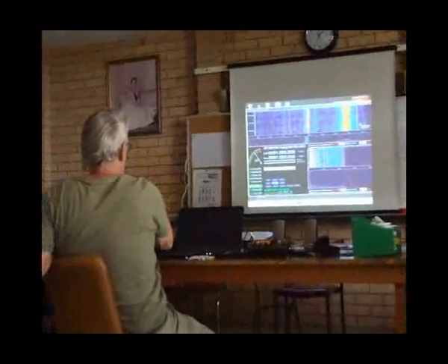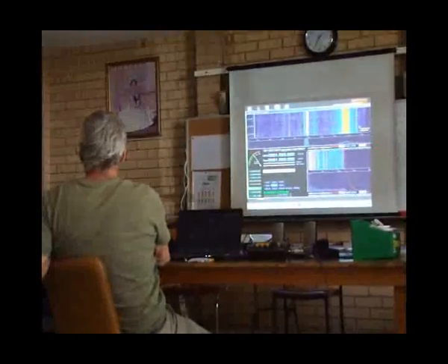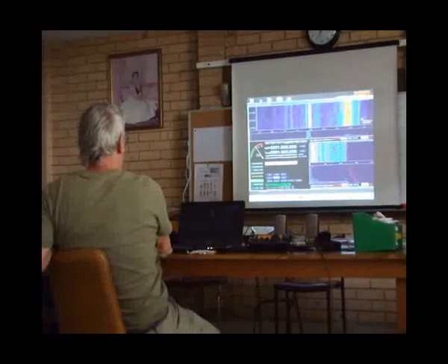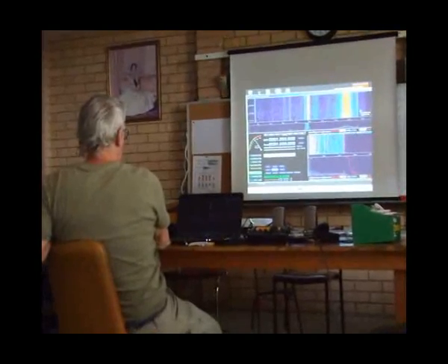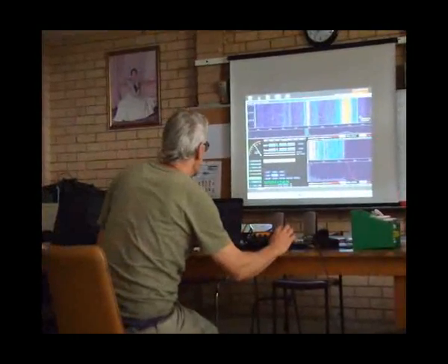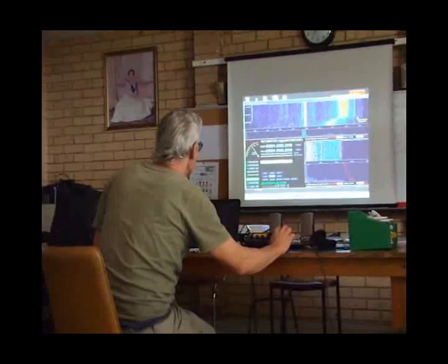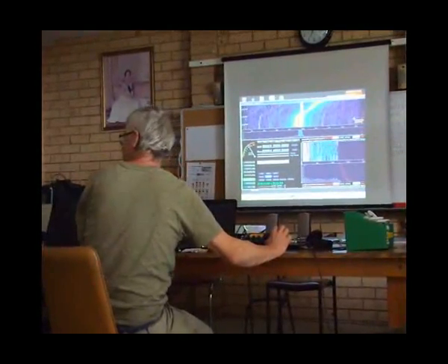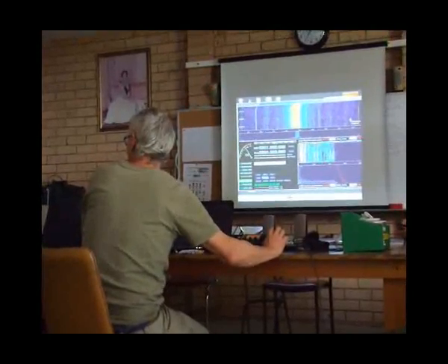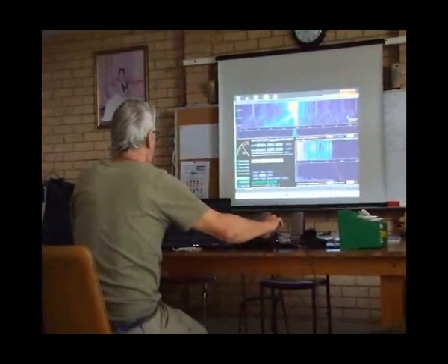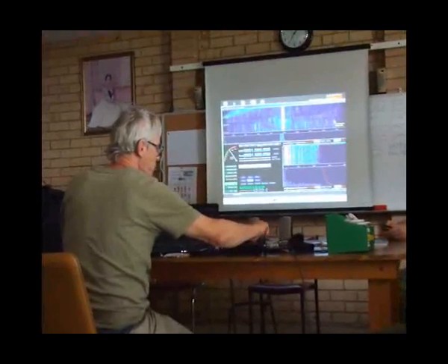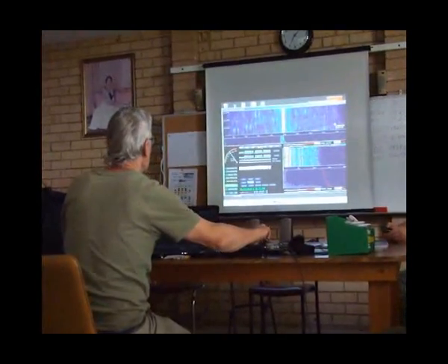Yeah, so on that spectrum there, you can see the dial readout between the waterfall and the spectrum. That's just kilohertz across the top there, and there's a bit of a signal there, see on the right. So I can just tune and bring that in. Okay, well, it's just noise, but unfortunately we need someone to go and transmit on 40 so we can find them. But the band's just gone dead as far as I can tell.